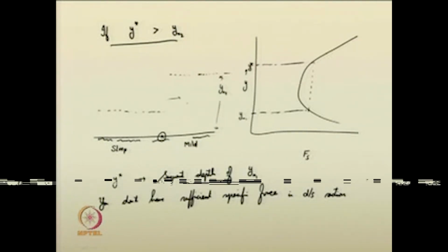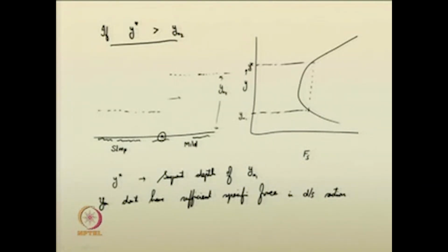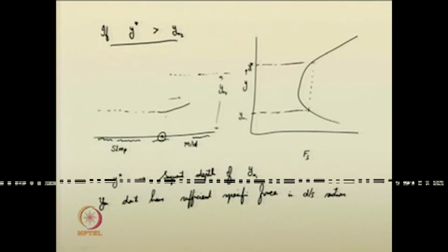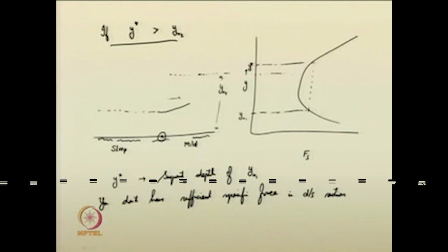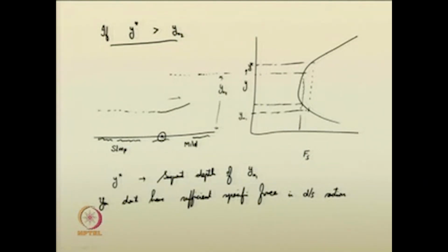That pushing is described through a gradually varied flow profile. It will be an M3 profile, as you know. The hydraulic jump will be formed, so whatever rise occurs here, say if water races from here like this through an M3 profile, you have to check the corresponding depth here. Up to this depth, the M3 profile will occur, here a jump occurs and it attains the specific force.